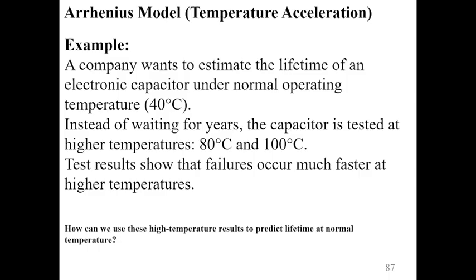Okay, this is one example regarding the Arrhenius model, temperature acceleration. A company wants to estimate the lifetime of an electronic capacitor under normal operating temperature, 40 degrees centigrade, and instead of waiting for years, the capacitor is tested at a higher temperature, 80 degrees and 100 degrees centigrade.